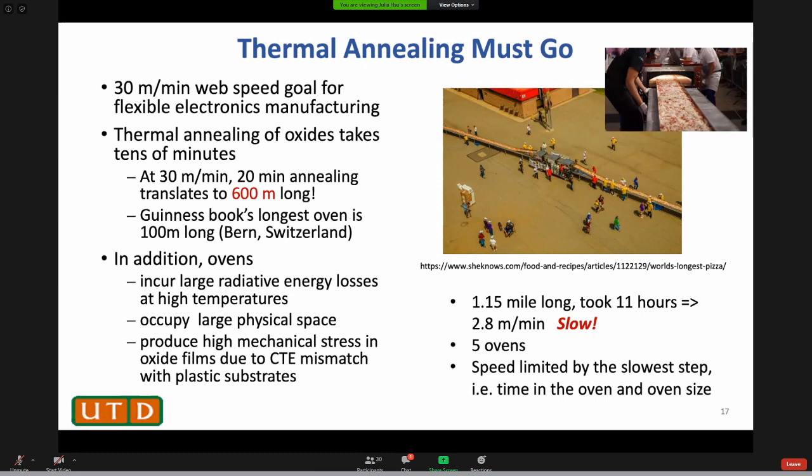So what can we do? I talked about thermal annealing to death now. There's something called rapid thermal annealing using infrared light. They have limited non-equilibrium heating. The substrate can remain at a lower temperature. And people have been using this, but still with a high CTE substrate, the substrate still heats up and it could cause cracks. And that takes minutes, not hours or weeks, but minutes.